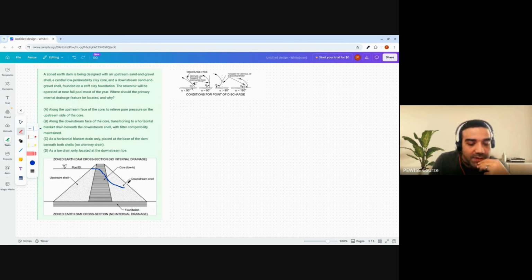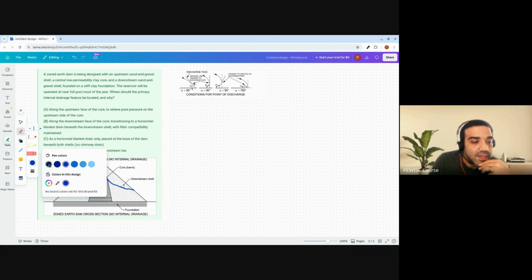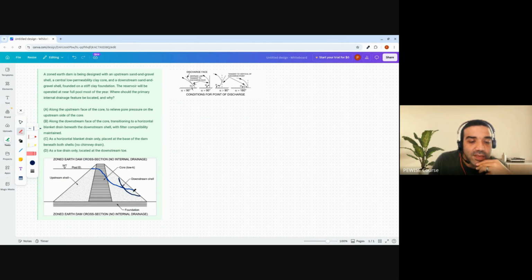And then if you don't have a drainage, this comes out like that. Let's use a different color. If you have a slope failure here, the flow and water table reduce the forces on your slope failure surface, and that causes problems. You may have problems at that point with a low factor of safety. So we put drainage to avoid this condition.